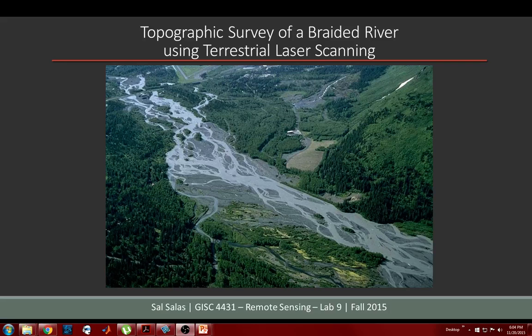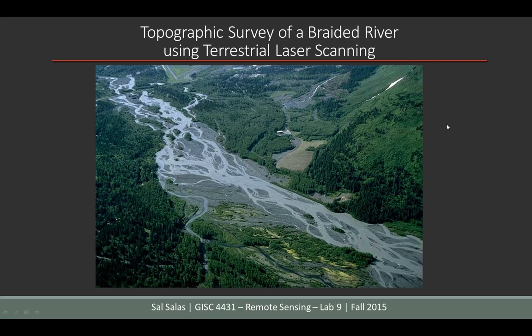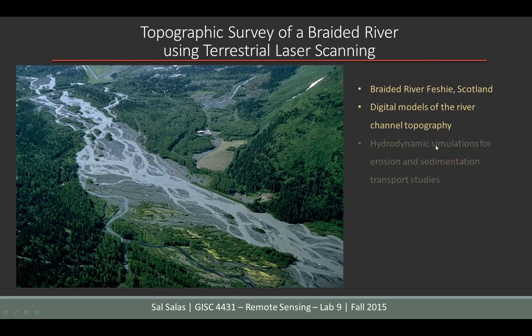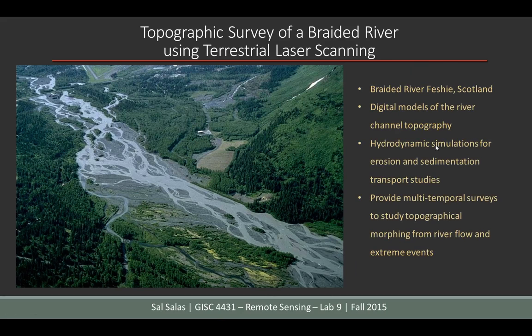My name is Sal Salas, and this is my lightning talk on topographic survey of a braided river system using terrestrial laser scanning. Now, this river system is the River Feshie in Scotland, and the purpose of the study was to create a high quality digital elevation model of the river channel topography. The DEM would be used for hydrodynamic simulations to study erosion and the sediment displacement.